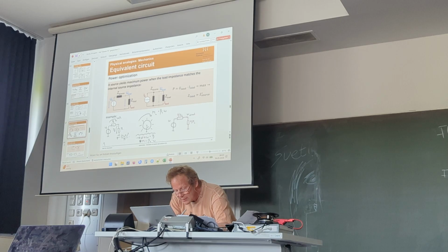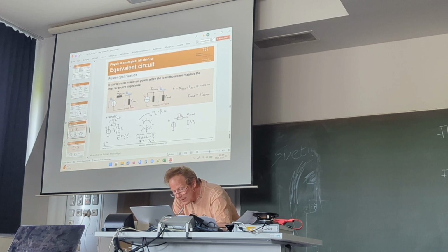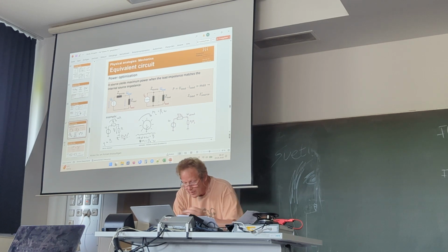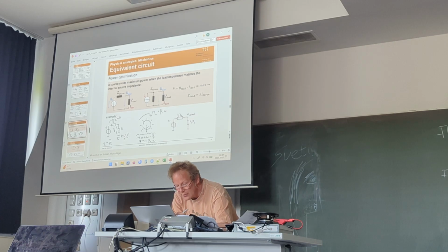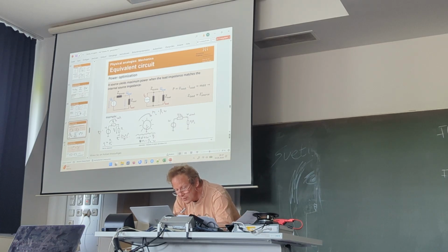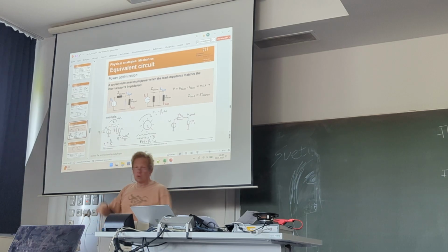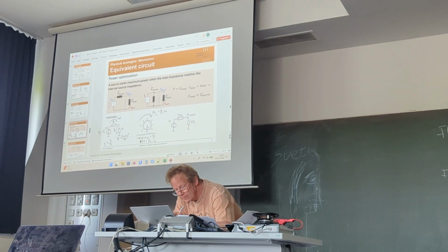Okay, so I write here. Eta is the coefficient of efficiency, so this is PL divided by the power that the source produces. This is the P0. Okay, and how much is that? The P0, again the same formula, voltage squared. So here is the complete U0 squared divided by the total resistance, in this case 2R. And then this ratio becomes just 50%.